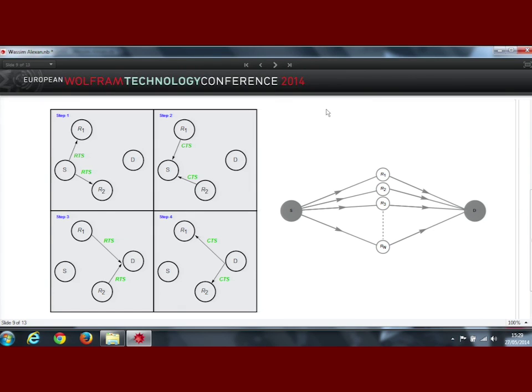It goes as this. The source node sends a ready-to-send pilot message, where this pilot message could be composed of any training sequence or any sequence of bits. The same sequence of bits is saved on all other nodes. So when the source node sends a sequence of bits to, for example, these two relay nodes, they compare the received training sequence or pilot sequence with the pre-saved sequence. By getting the difference and comparing the received set with the saved one, it can estimate the channel fading coefficients between these paths from the source to each of the relay nodes.